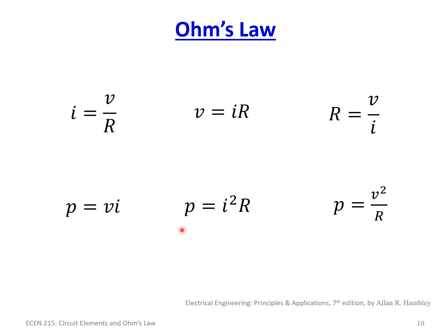And hence this is why the level of current going through a wire is a very important thing. You probably know that the voltage on high voltage transmission lines, taking the power to and from a generating plant to a city, for instance, is not at household voltages like 240 volts. It's actually like 500,000 volts. Well, this right here is why.